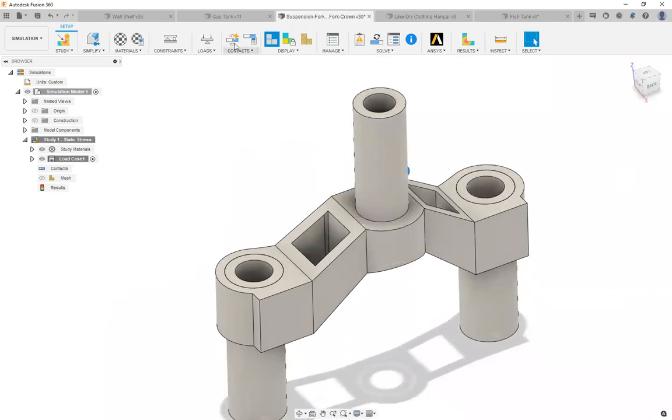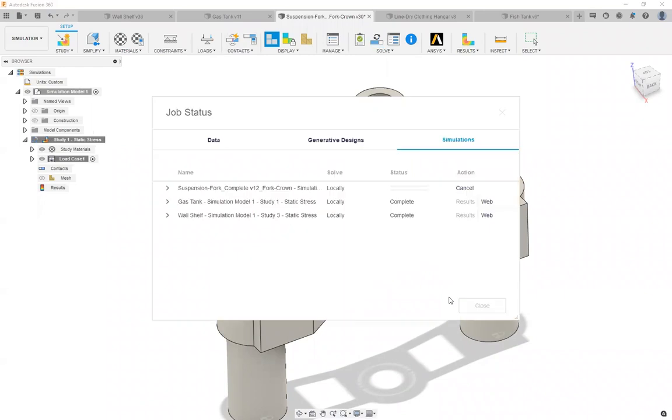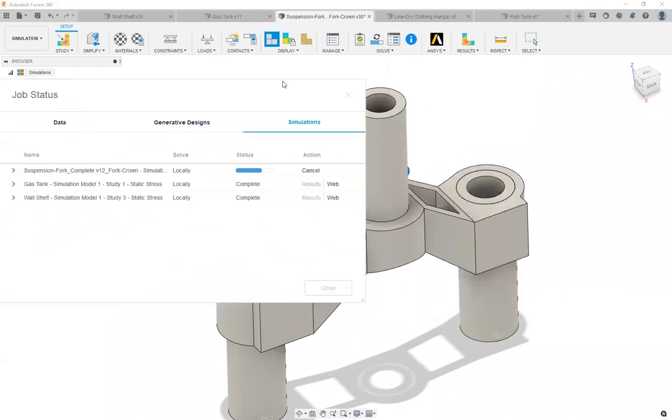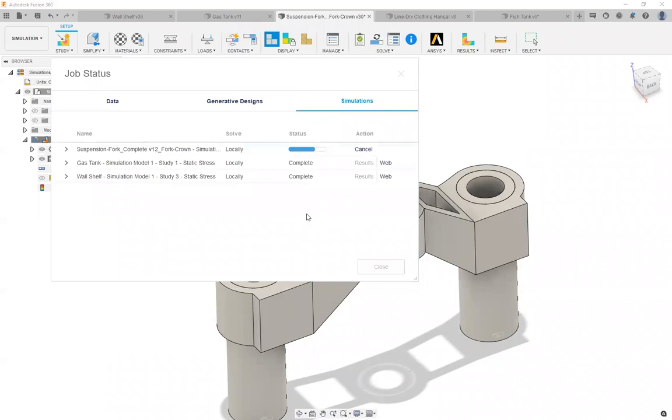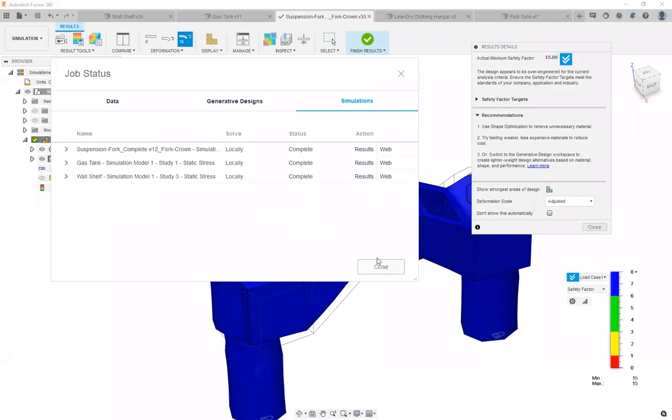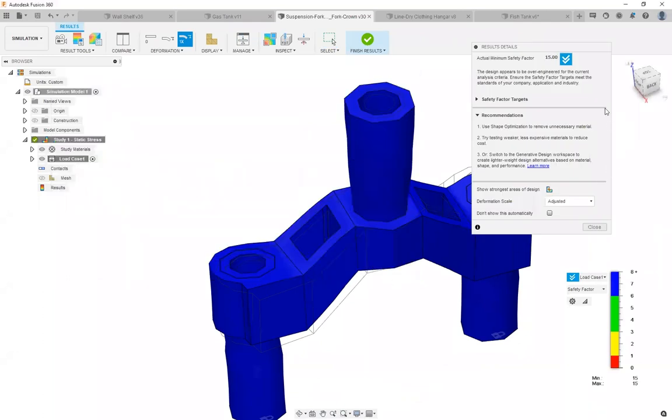And then after that, let's go ahead and generate contacts for anything closer than 0.1 millimeters, I think it was, which will be considered almost glued together essentially. And then we'll go ahead and solve for this, and we can see the results of a moment applied to our fork crown. Everything's done locally so far. I'm not sending anything to the cloud, just because it's sometimes actually faster to do it locally than to send everything to the cloud.